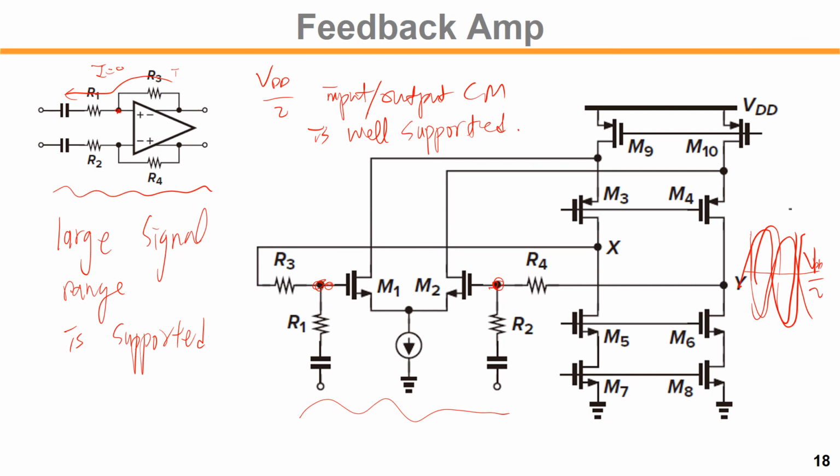Again, there is no CMFB shown here. There must be CMFB circuitry, so we have to take out the output, let's say X and Y, and some reference voltage.